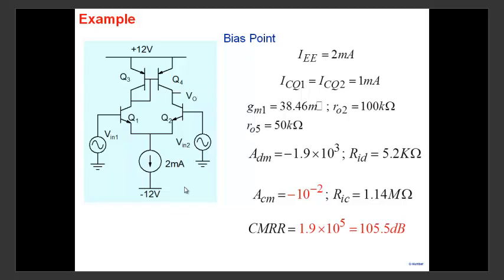So I've shown you here an NPN differential pair with a PNP current mirror. You can of course do a complementary version, in the sense that you could take a PNP differential pair with an NPN current mirror. You can just flip it and you'll get another configuration.